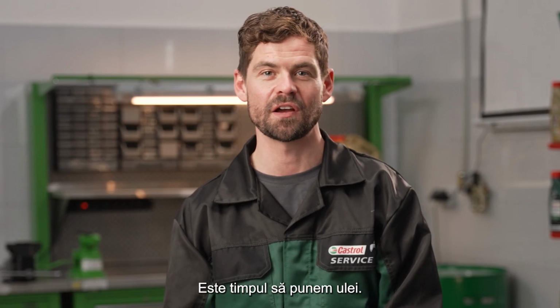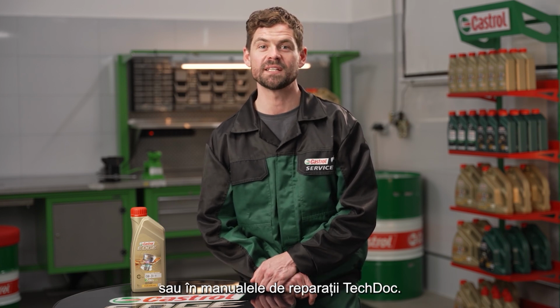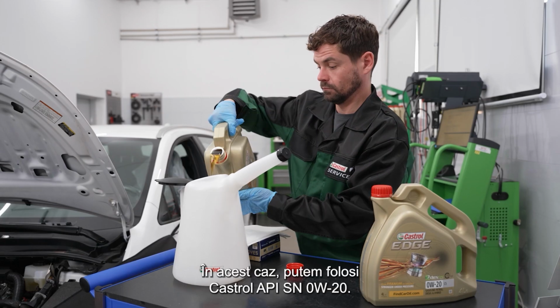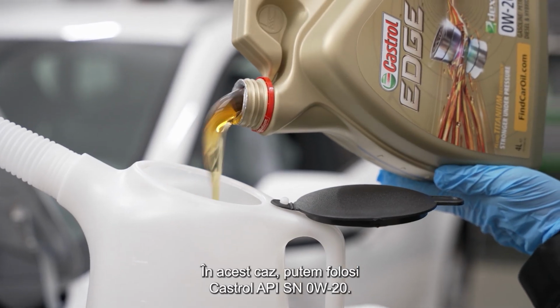Now it's time to fill the oil. You can find the required amount on the maintenance schedule table or in the Tech Doc repair manuals. In this case, we can use Castrol API SN 0W20.